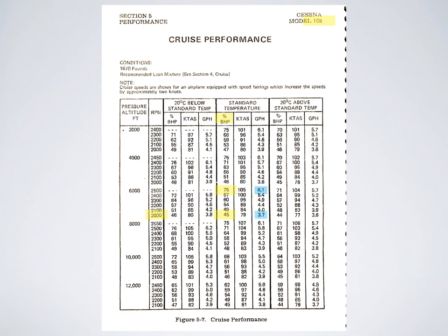So there you have it. You know from the range profile chart that you find the power setting that will give you the maximum range, which in this case is 45% power. Select that for your en route power setting, and that will give you a fuel burn and a true airspeed for that flight.